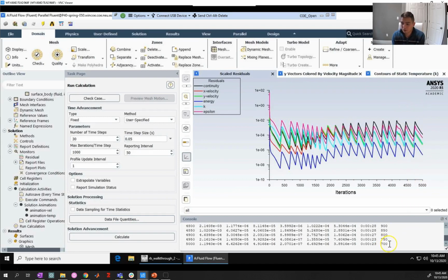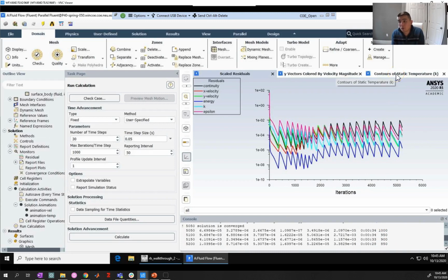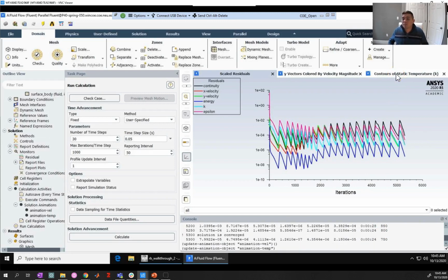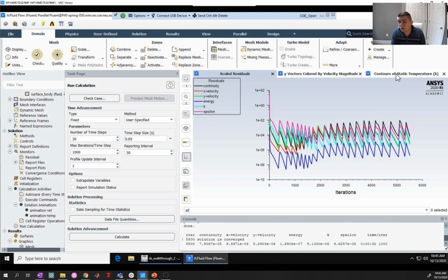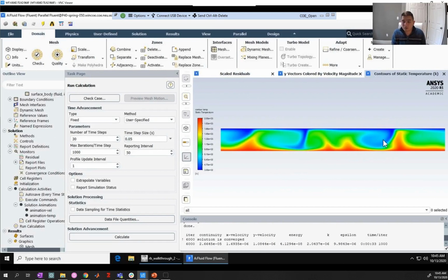So evaluating here, it looks like it's about 300, 350 iterations to reach convergence to the criterion that we've set. For the homework, we've set a maximum number of iterations of 100, which means for some of your time steps you may not reach convergence, which for just the homework exercise is okay, but obviously you want to be a little bit careful with how confident you are with the results for a simulation where you don't reach your convergence criteria. Okay, so looking back at the temperature, we now have far fewer ups and far fewer downs, so the number of convection cells has decreased as well.